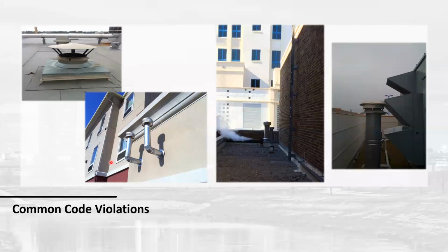We call this the Texas Special. So we have a lot of 3-story apartment buildings with single-story mechanical rooms. They replace the roof, and then they want to put water heaters in there. So they put Category 1 tank type water heaters, and they blow them out the sidewall with B-vent. B-vent is not a Category 1. You cannot go sidewall with Category 1.